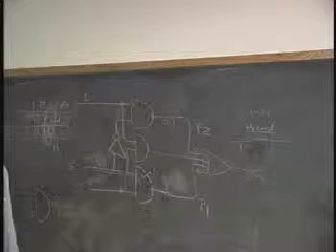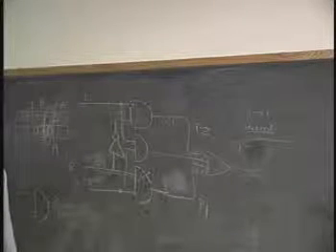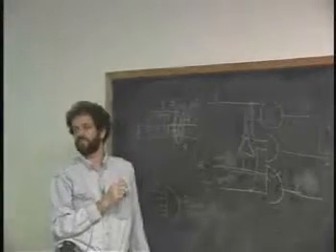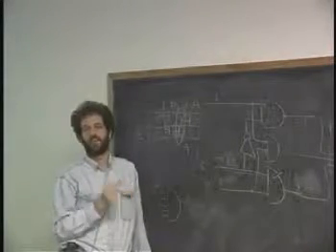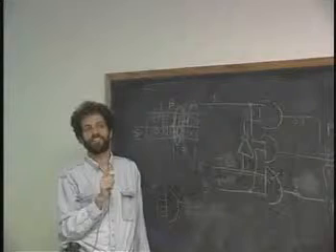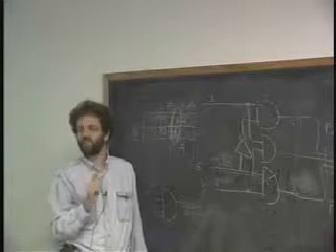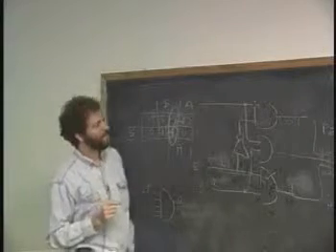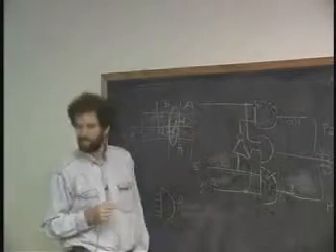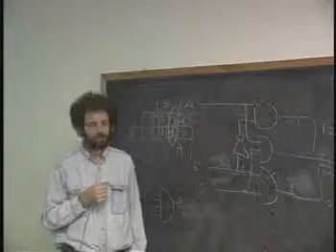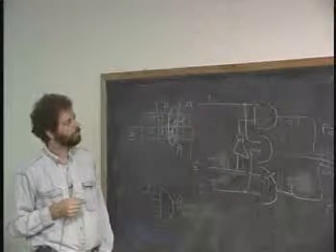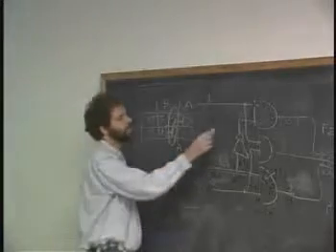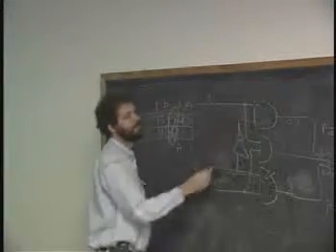So how could the output glitch? It can't. It's an amazing thing. So sum of products cannot generate a 0 to 0 hazard. Now, it's almost true. Okay? You see, I'm still getting that quizzical look, right? Does that occur when we're going up through the change in S gate? Except that if this changes from a 0 to a 1, yes.